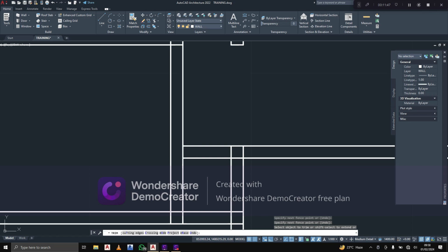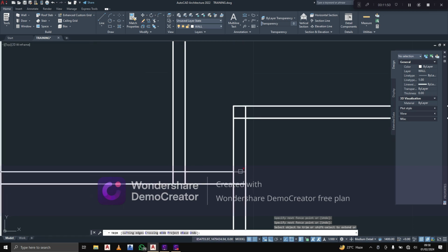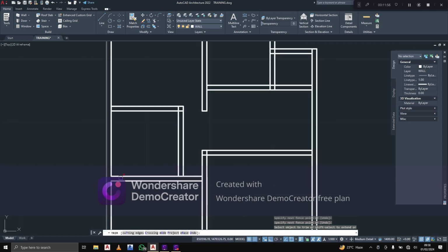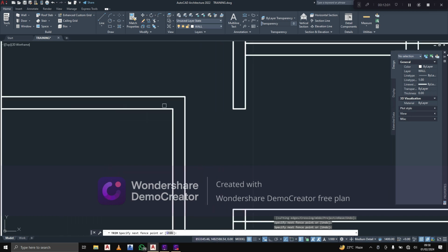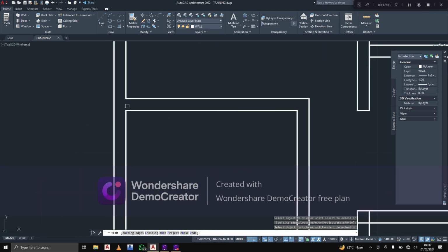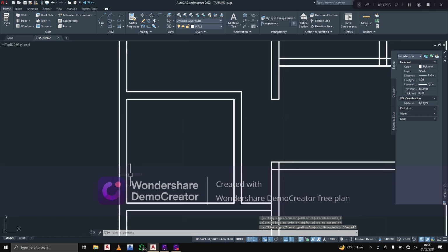divide them equally. Now for you that are finding it difficult to get the midpoint of your line, you are yet to turn on one tool that you ought to turn on. So I will take you down. Pick your line and locate the midpoint. You see, I'm unable to find my midpoint. It is giving me the snap at the edges. You just come down to the snap tool. You can see this tool.